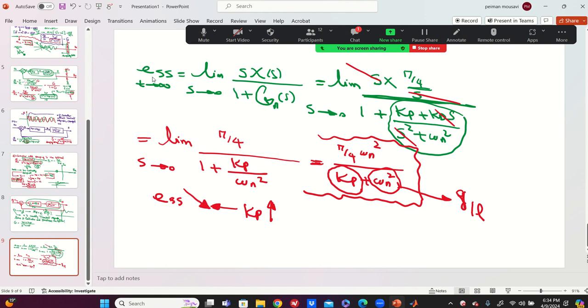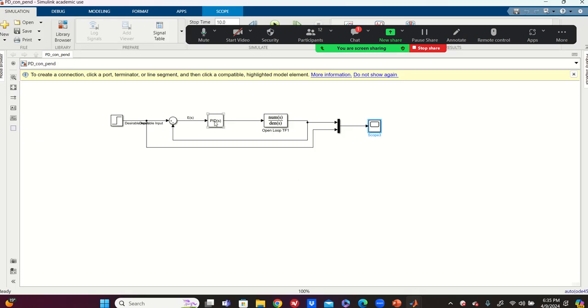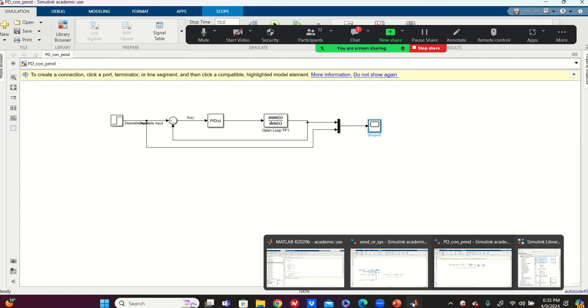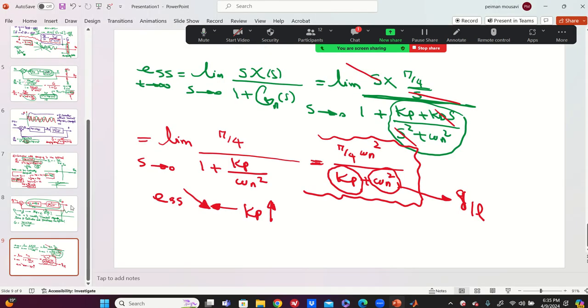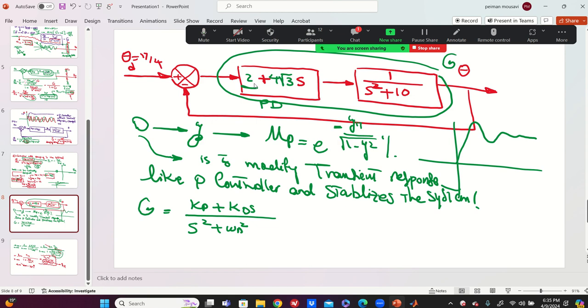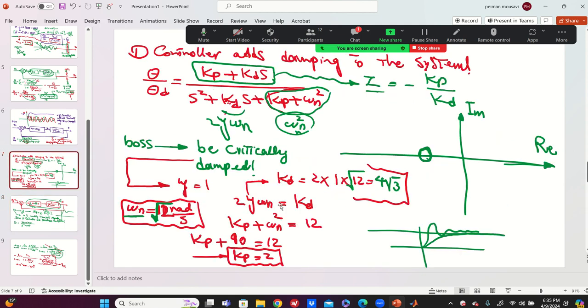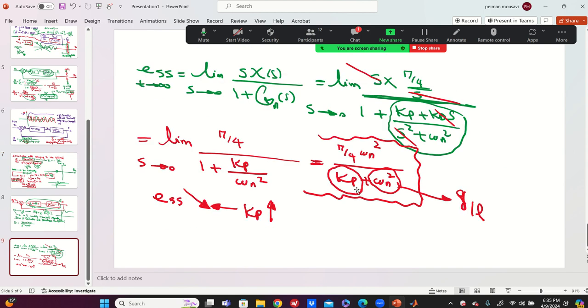Yes. So we saw P and D, but I'm going to teach you I next class. I didn't teach you I yet, that's why I played with PD here. When I teach you I, maybe we don't need to change P and D. We have to stick to our original design, these two numbers, because the I function of control is to remove the steady state error signal. So if I add I, I'm going to stick to this. I'm going to show you, based on whatever we designed with the correct numbers, and the I is going to fix it. We don't need to play with the Kp.